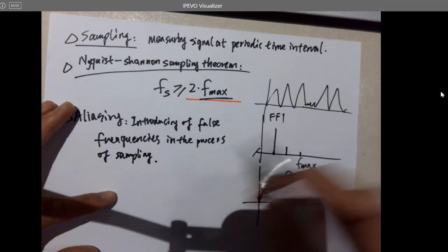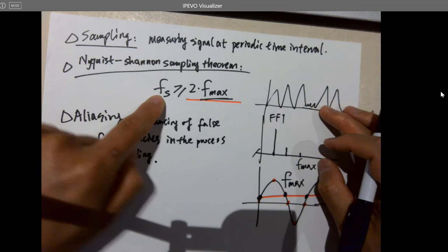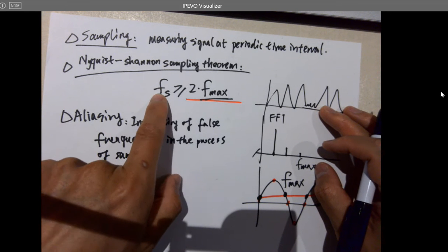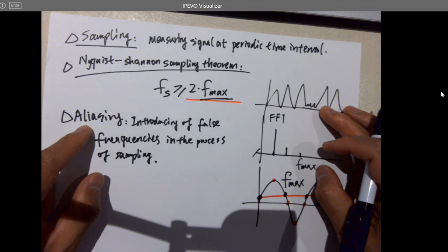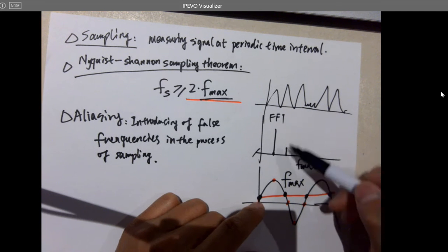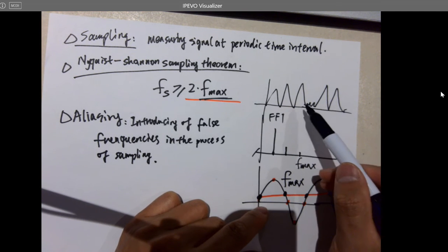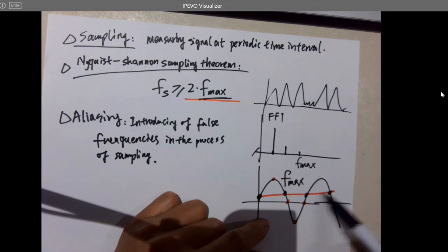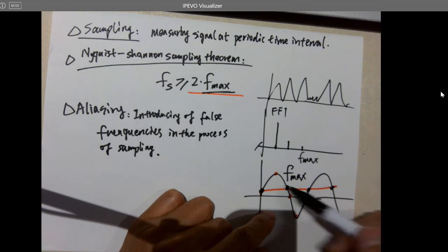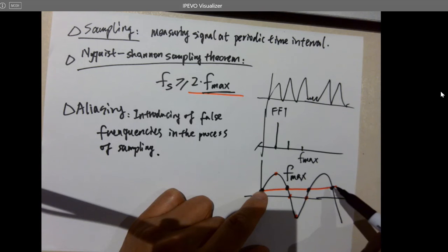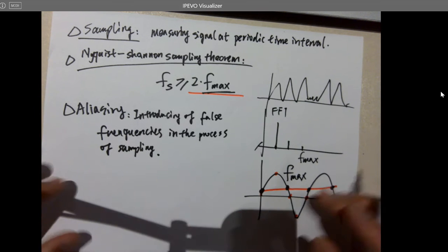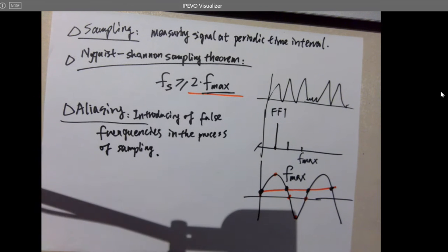If you have a low sampling frequency, you are going to see aliasing in your recovered signal, because you cannot recover all the frequencies of the original signal. It's giving you a line. The frequency will be totally different. There's no such signal with that frequency in your original signal. Okay, just some concepts you need to know.